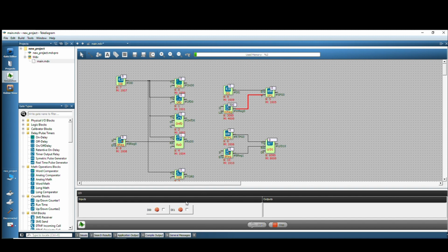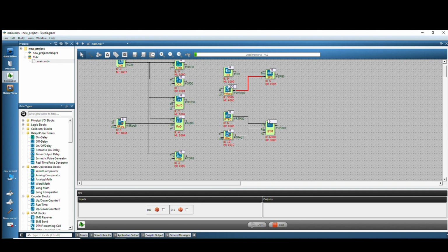We activated the enable input, and it started generating a pulse per second. We can increase this period. If we want 2 seconds, I can enter a value of 1000 milliseconds. This way, it will generate a pulse every 2 seconds. We can increase or decrease the period duration like this from outside. And when we set digital input 1 to position 0, it will stop generating pulses.